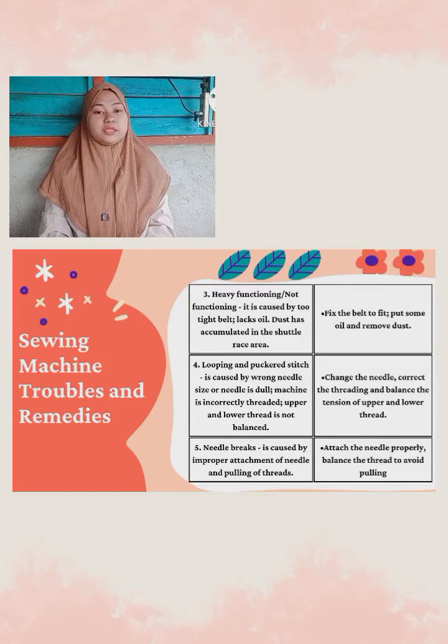Then the needle breaks. It is caused by improper attachment of the needle and pulling of threads. So when the needle breaks, it could be due to not putting the needle correctly in the machine. So what we can do is attach the needle properly and balance the thread to avoid pulling.